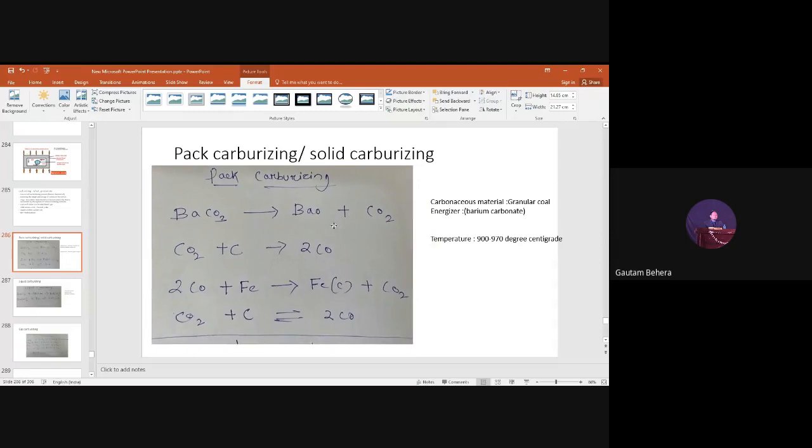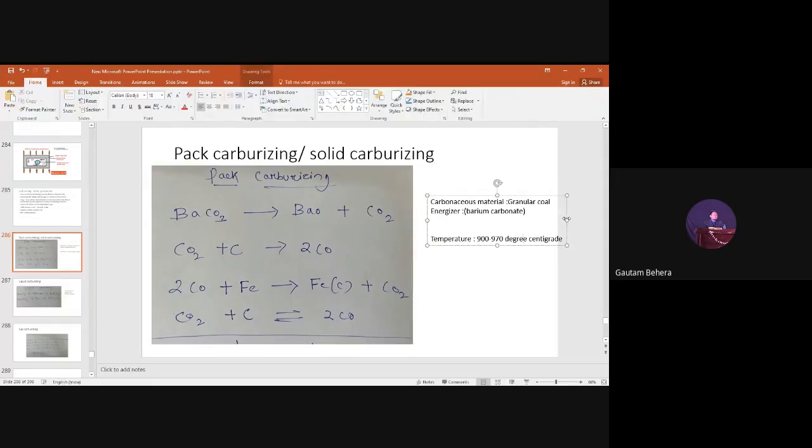So this is the temperature, the heat up to which we will heat the steel box, and then the time duration or holding time. Basically we choose 7 to 8 hours, or it depends, you can make it more, because you have to remember this time is also important.